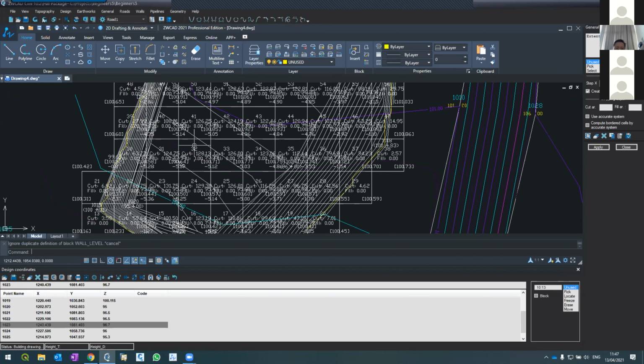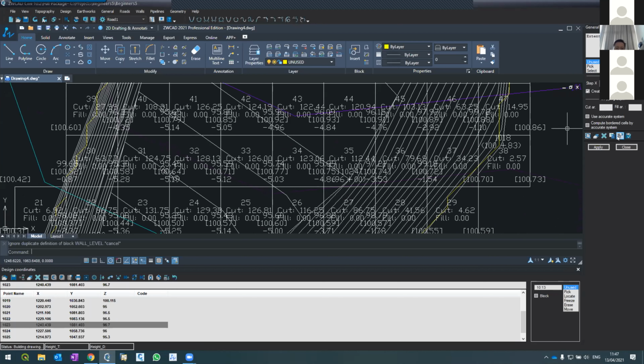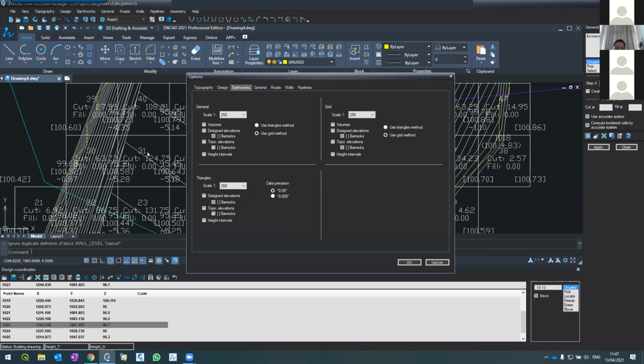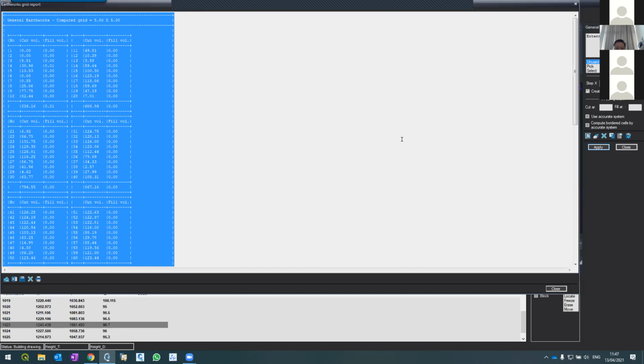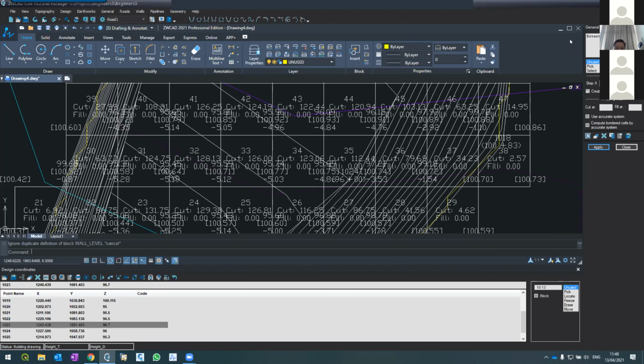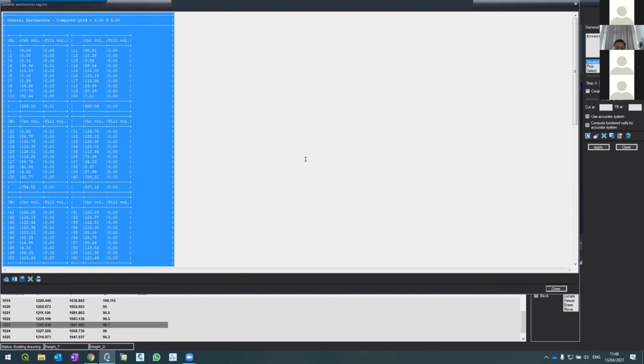You see the text in the grid is too big, so I'm going into the options in the grid on the right, general, and change it to smaller. Let's make it 200. And I apply again. Sorry. To effect changes, I need to do something, so let me remove the create and press again. Now the software will know that we need to recreate. Okay, let's see what happened.